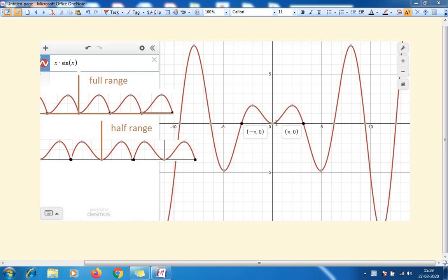Now by full range Fourier series we mean that we'll take a certain section from 0 to pi, or possibly 0 to 2 pi, in whichever manner it is required. Now we have chosen 0 to pi, which means the section of the curve from 0 to pi shall be repeated along the entire time axis as shown here. As you can see, the resultant waveform doesn't have any symmetry. So we'll have all the terms, a naught, cosine terms and sine terms.